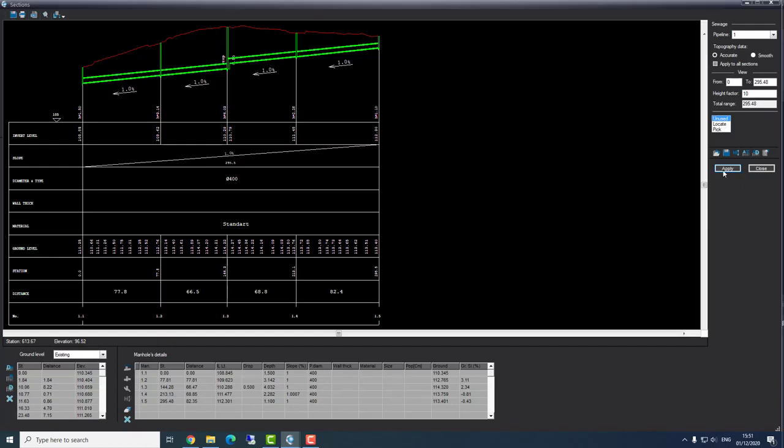Now I want to add the manhole size. We will do it through here. Here we will define the size of the manhole itself. If I want, I can use this to calculate it automatically. If I press it, you can see that the system used some predefined criteria to automatically fill in the size right here. The star means it's round, as we chose in the pipeline list.